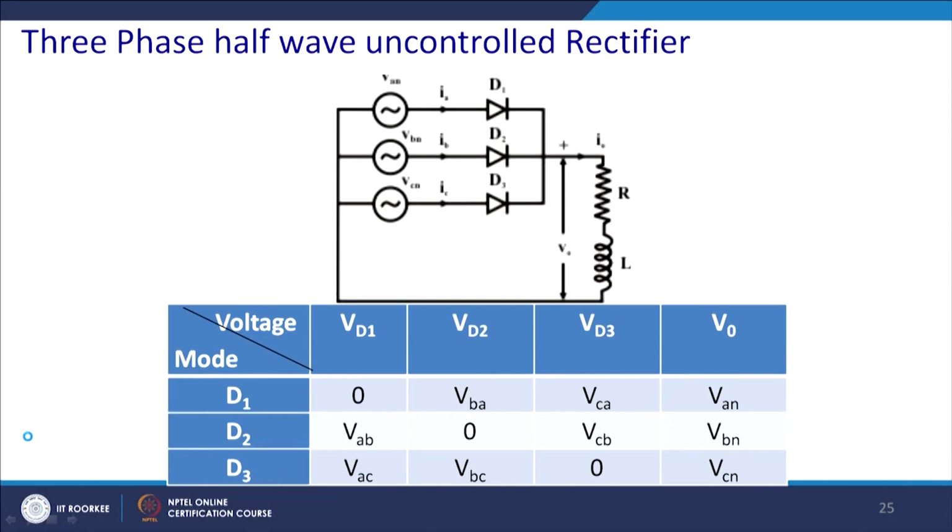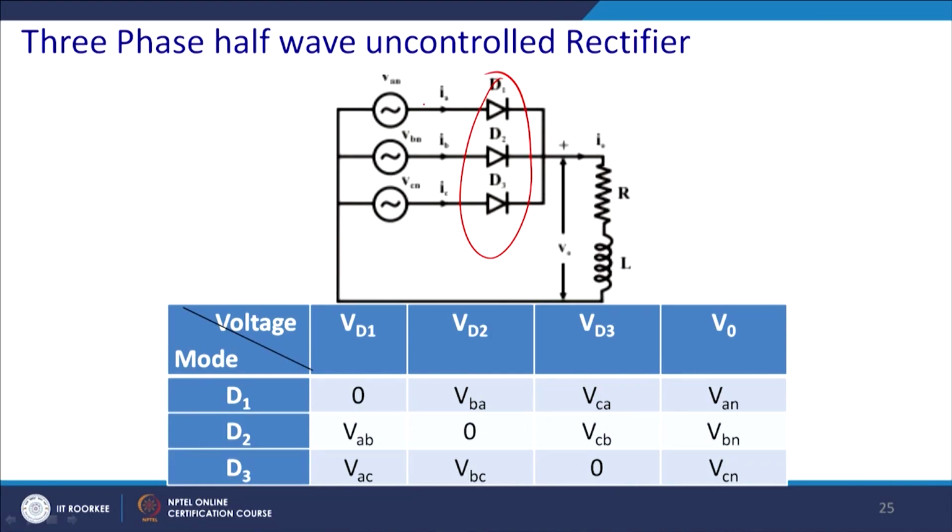Since our supply is a three-phase, three-wire or four-wire system, it makes sense for high power applications, for the DC motor, mostly this kind of application, where we convert directly from three-phase to DC. So, this is the application part of it. We use a three-phase half wave uncontrolled rectifier fed through diodes, and it is feeding, let us assume, an RL load.